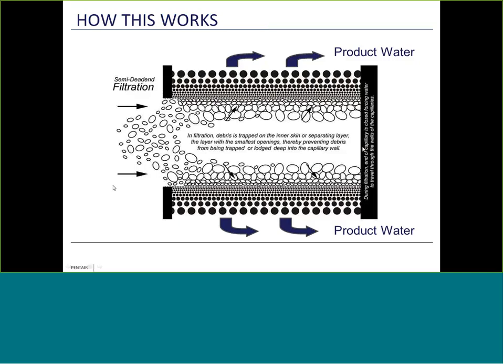A lot of these systems are placed on moderate dirt load waters with very high volume use, simply that the load of dirt coming in is quickly fouling carbon filters or pre-filters to a point, and an ultrafilter makes sense based on the volume of water that a customer uses, or they're used in areas with high dirt load or high use of flocculants, and the UF cartridge will help protect the carbon filters behind it from fouling from heavy dirt load or flocculants.